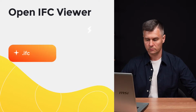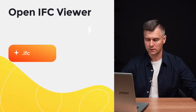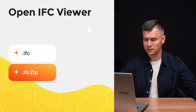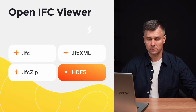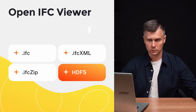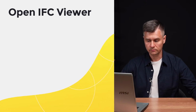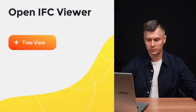When speaking about the properties panel, for instance, it is implemented using a common data access interface and the ability of opening IFC models not only from a STEP physical file, that means the IFC extension, but from, for instance, compressed IFC zip, or from IFC XML or HDF5 representations as well. So this all is available, and it's necessary to say that a set of quite sophisticated plugins is part of the Open IFC Viewer.